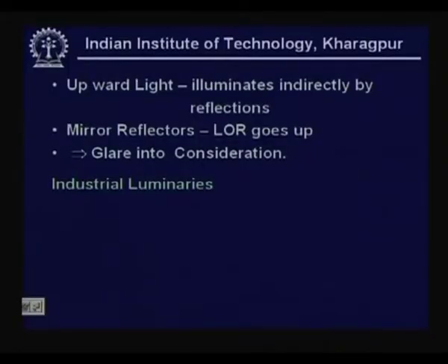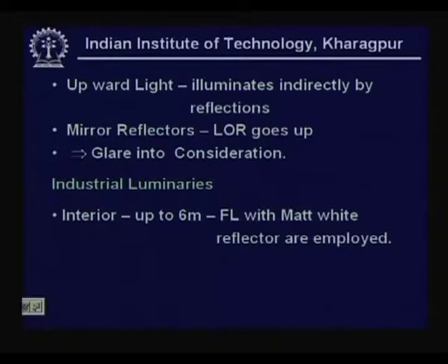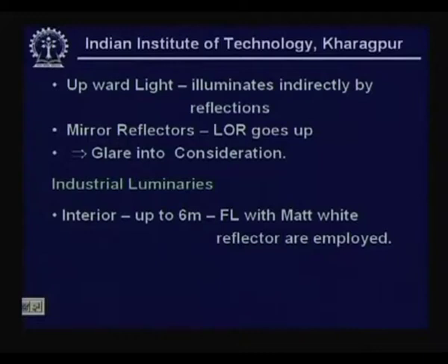The next issue which I mentioned is industrial luminaires. Essentially, the height of an industrial bay depends on the type of manufacturing process and the volume of the material that they have to handle. Industrial interiors reaching up to about 6 meters can be lit using fluorescent lamps with matte white reflectors.